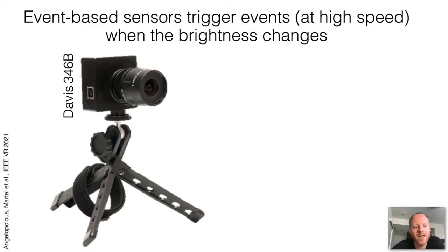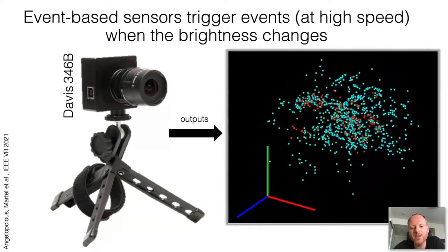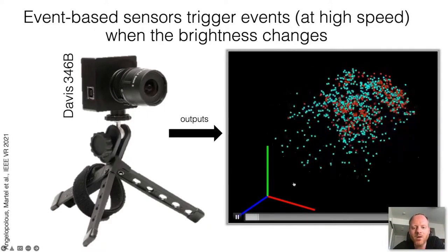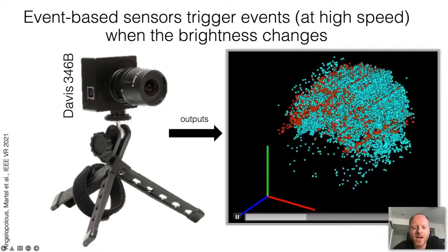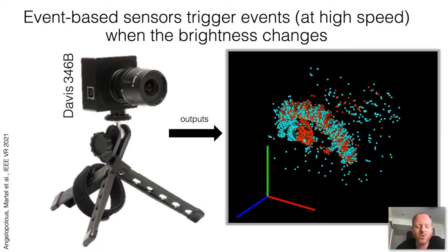It basically reports an event per pixel with its XY location and polarity whenever the temporal gradient of a pixel exceeds a certain threshold. And that is perfectly suited for this eye tracking solution, because if we look at the same video that we just looked at, there's going to be a bunch of spurious events, but most of the events that we're actually recording are on the moving pupil and maybe on the eyelashes and so on and so forth. But most of the rest of the image is just blank. So we don't ever have to read out that data. This is an asynchronous thing, and the events are generated as they happen. So this isn't being read out at a fixed frame rate. And it doesn't have a fixed bandwidth.